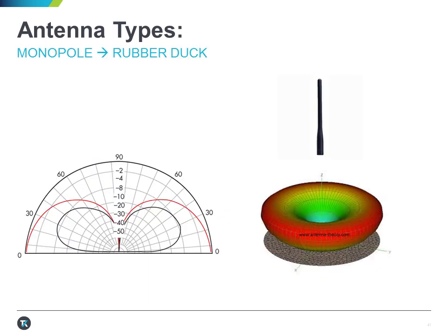By comparison, a monopole antenna, or in this case a rubber duck, has a much different antenna pattern compared to a dipole. We have to understand that it essentially has half the antenna pattern as the dipole does. Curiously enough, while the horizontal antenna pattern is quite uniform, the elevated or vertical antenna pattern has a big null in the very center of it. This means that we can actually use this type of antenna for what I would call inverse direction finding, meaning we go for the null in the signal and not the peak of the signal.